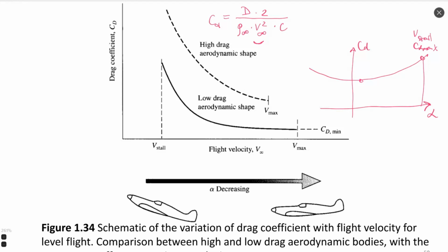According to this equation, by increasing the aerodynamic coefficient, we automatically decrease the velocity of flight. In this case, it's more visible, I think, because drag D is a value that is acting against thrust. So we need to have thrust of the engine, power of the engine, corresponding to the required drag.